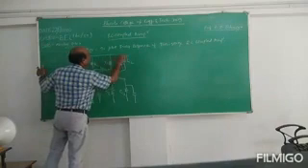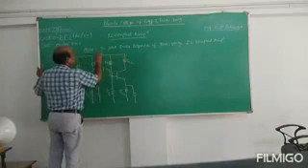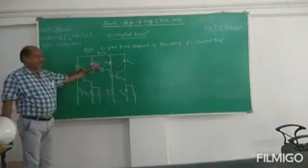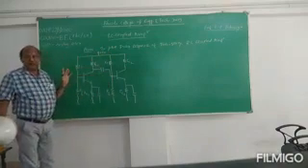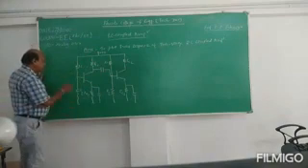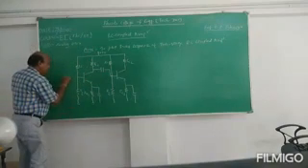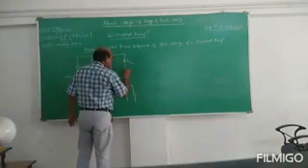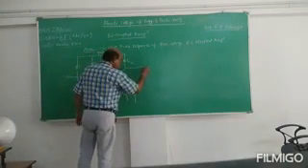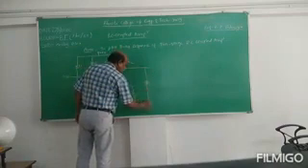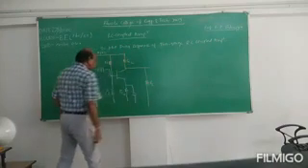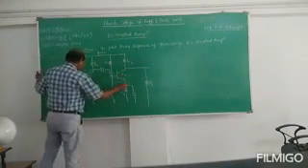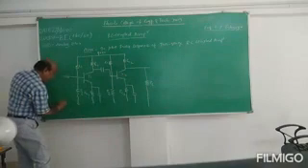First, you connect this to the plus 5 volt DC supply for the biasing of this transistor and this transistor. Then use the coupling capacitor over here, and take the output across the load resistance. This is transistor T1 and this is transistor T2, and this is the common ground.